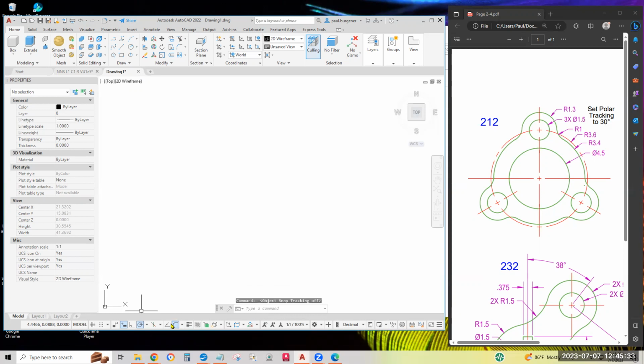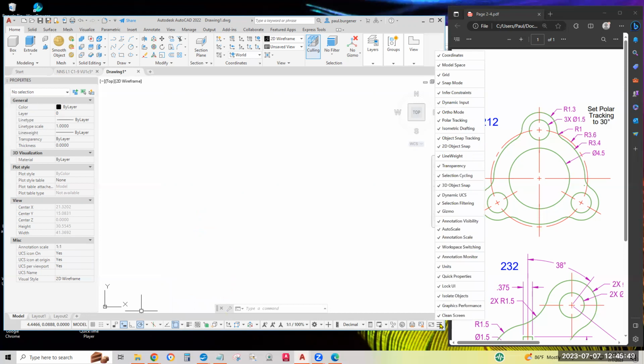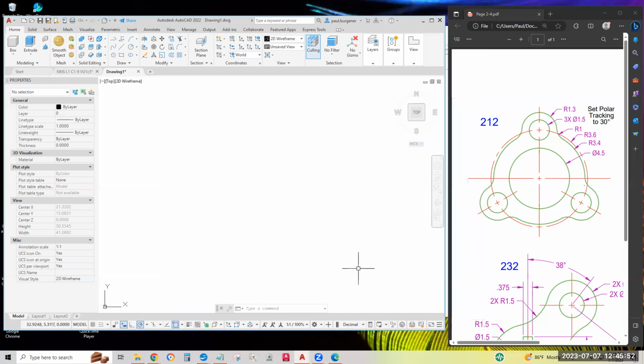Whoops, I don't need polar track. Osnap tracking is not on yet. They'll teach that in intermediate. And Osnaps are set for the usual 5: endpoint, midpoint, center, quadrant, and intersection. Double check all taskbar buttons are visible, so nothing is turned on that I don't know about.